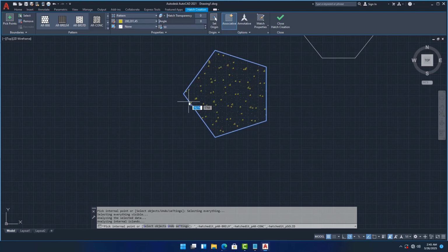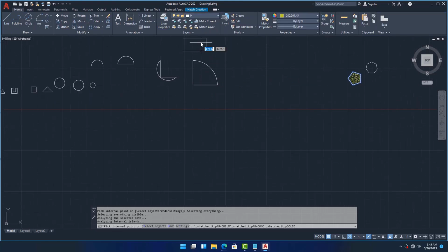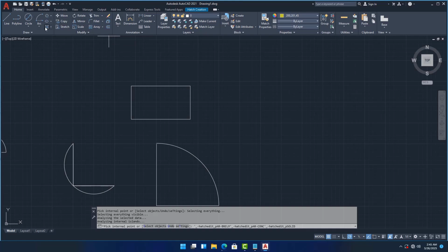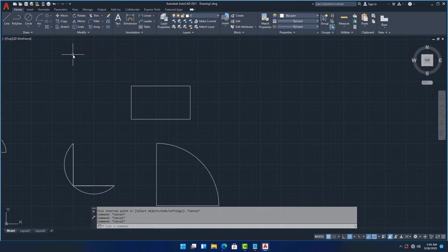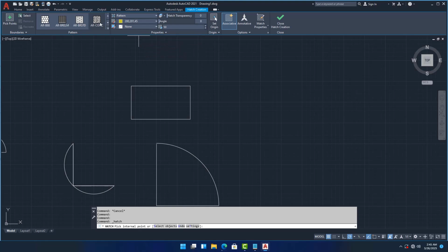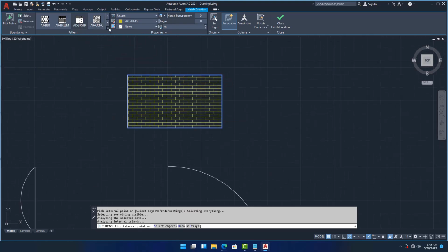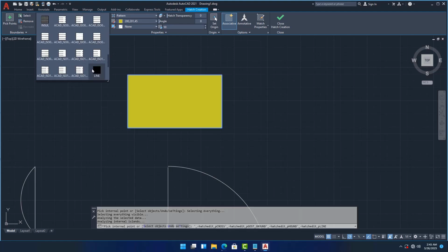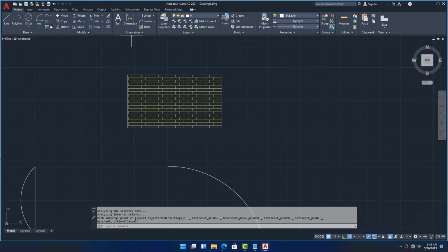So now maybe let me hatch another place again. Let me hatch this. Click on hatch. Click on hatch again. Let me click on escape. Then click on hatch over here again. Let me use Greek hatch. Do you see it? You can click on anything over here. There are many types of hatch over here. So the next one is, once you go to your hatch over here, just select it. There's a gradient hatch over here. The gradient simply means like a solid.